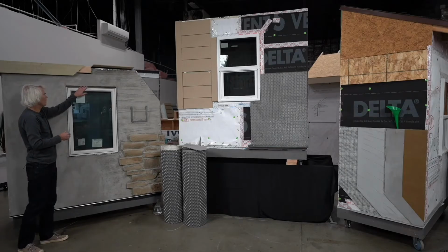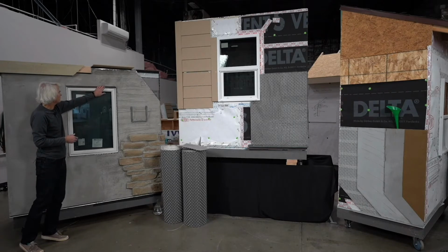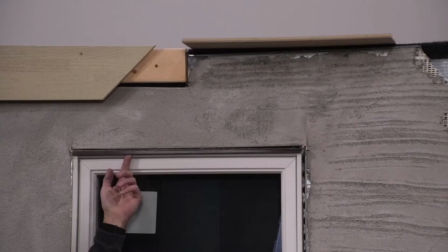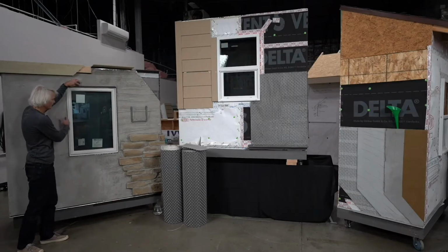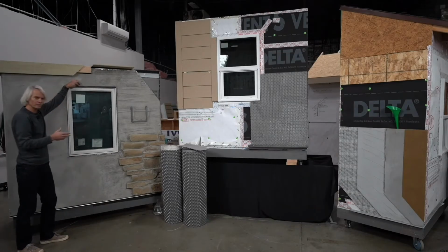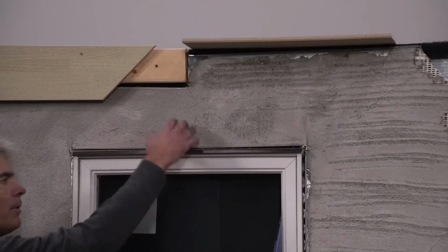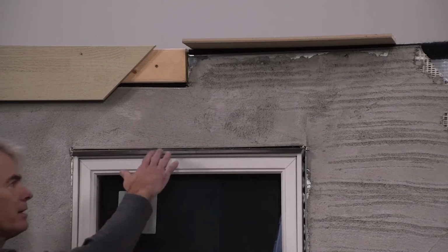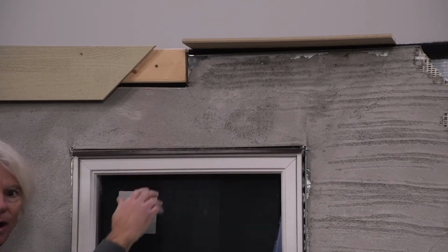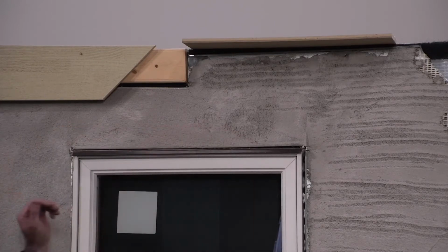And at the top of the wall, we've installed that same casing bead, but here you can see this brown piece. Just to highlight it, we've integrated a drip cap flashing with the drip edge on it. This joint we will not backer rod and caulk. We'll backer rod and caulk these 3 joints, mostly for aesthetics and to seal out water or other things. But up here we want to allow for the free drainage of water, and in some cases we may even want to use that as a ventilation intake or output on the building. So that's a critical one. We're not going to caulk that joint at the top.